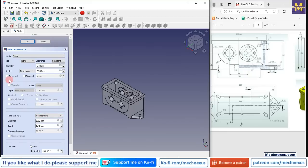So once I select the counterbore, here I will provide my through drill diameter, which is 16 mm, and this will be through all.